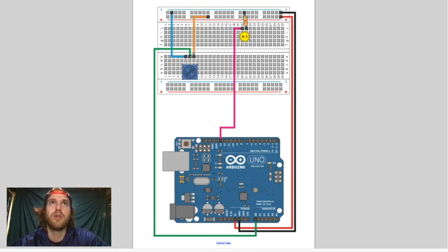With the potentiometer, we are reading the voltage value created by the resistance when we turn it, and it changes. So if you turn it all the way down, it's going to read 0, and as you turn it all the way up, it's going to read 1023. Okay, so that's being put into port A0 right here. So that is an analog in. We are reading a range of values, and we're taking it into the Arduino so we can make a decision. You'll be doing some decision making today. Okay, so then what do we do with that information?